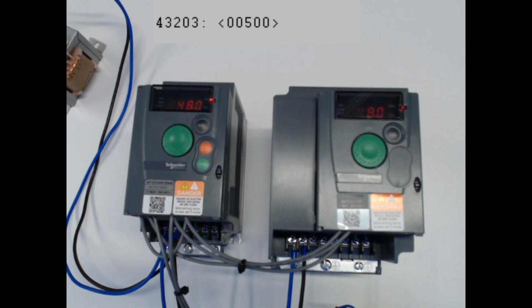All right. So as you can see, now if I increase to 0.4 difference, they start to affect the PID. The PID is very, very sensitive. My sensor modulation is of course not going to be as perfect as a real world scenario. In the real world scenario, it is just beautiful. You can't even see the pressure gauge move. This is how accurate it is, right?